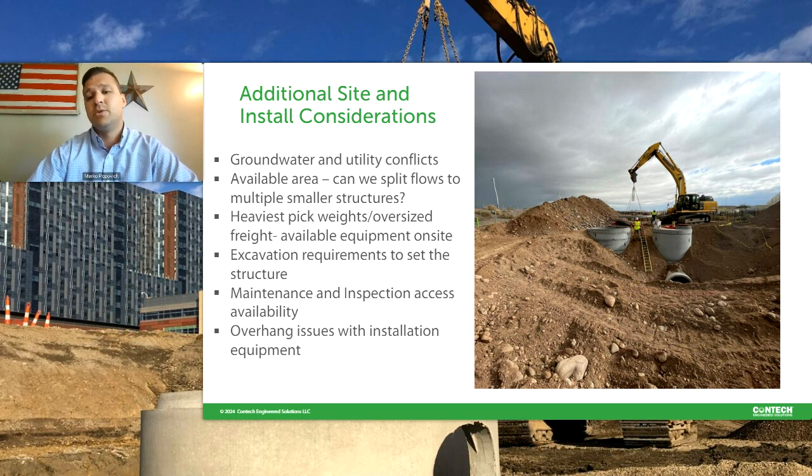And then ultimately, I put my hard hat and steel toe boots on. What sort of equipment's on site? Do we have a crane? What's our heaviest pick weight look like on one of these units to actually set it down in the hole right off a truck? Do we have access for a truck to get it on site and safely maneuver around there? And ultimately with that, what's above those cranes? What's above the boom on an excavator, even if that's what's setting these units? And can they properly maneuver around site without worrying about a power line hanging over the piece of equipment, or being on an airport where they have to be aware of clearance? All of those should come into mind early on in the design process.